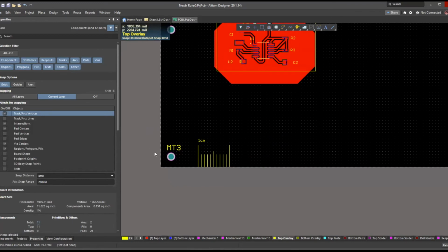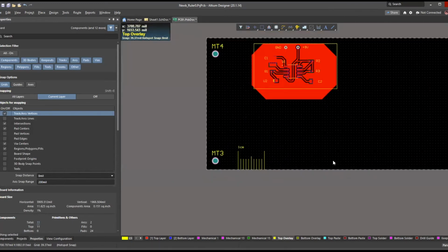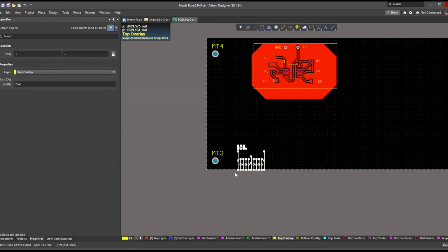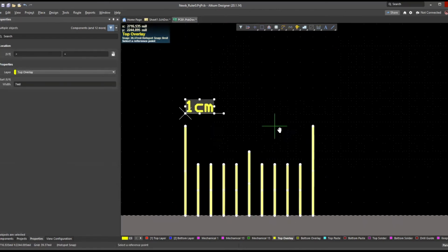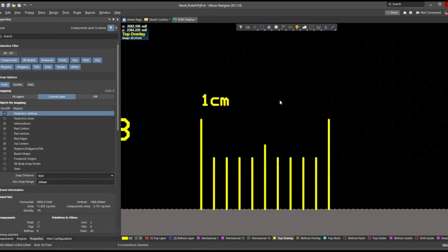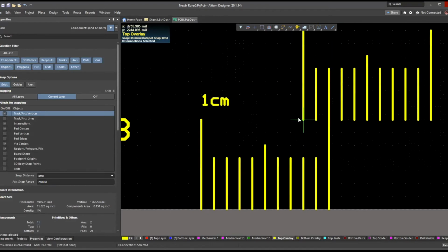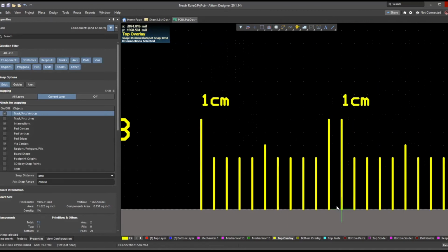Cool. So instead of doing every single millimeter, I'm just going to select this, Control copy, and when you're copying something, you have to define the reference point for the copy. So I'm going to define it as this here, and then notice that when I paste, my little selection tool is at that end where I defined it earlier.